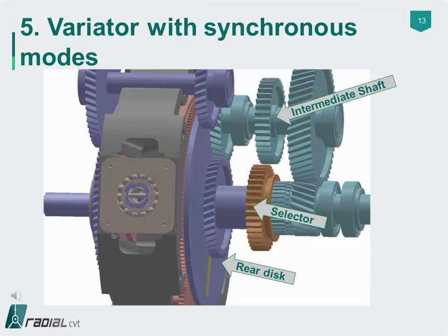Synchronous modes refer to the shifting or engagement of components rotating at the same speed when changing from one gear system to another. Synchronous mode shifting can be done very fast since all components rotate at the same speed, resulting in minimal power interruption when done via dog clutches. When engaging and disengaging clutch packs are involved, the clutch action can overlap and power will not be interrupted at all, as is done in dual clutch and automatic transmissions.